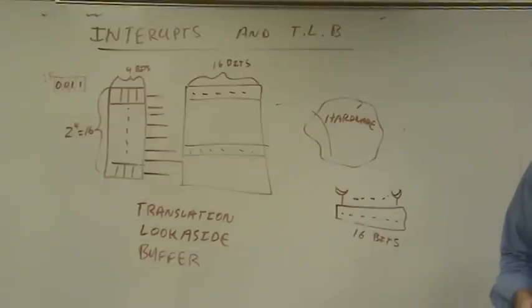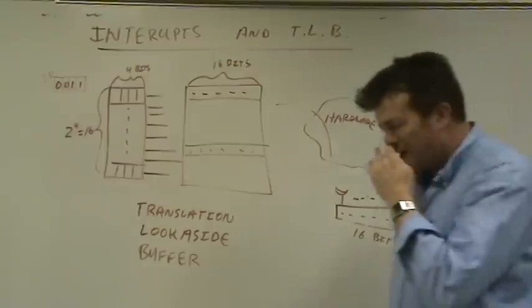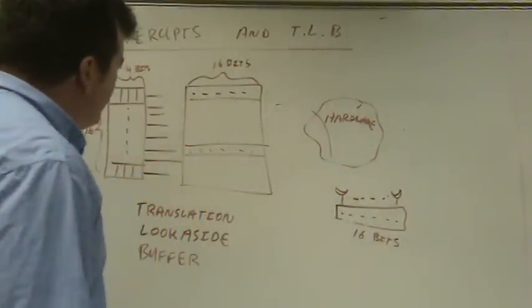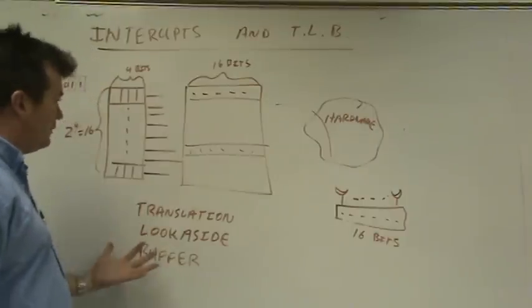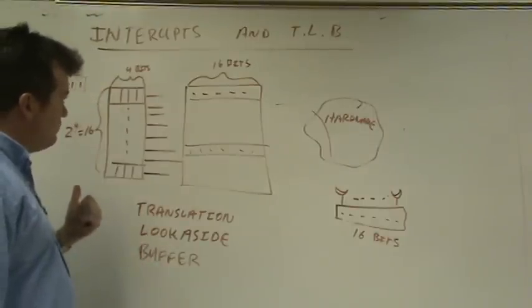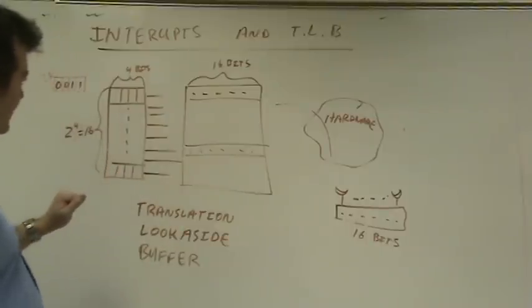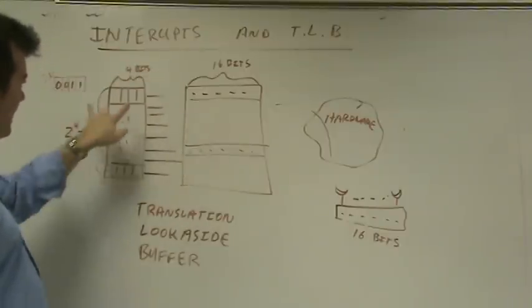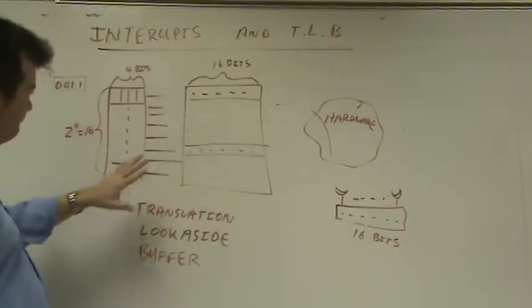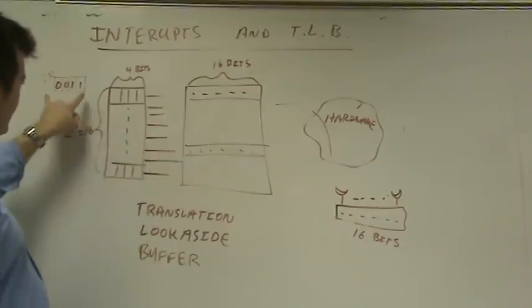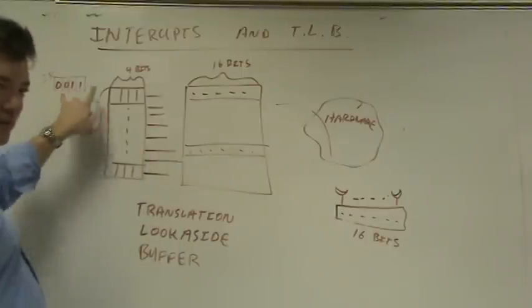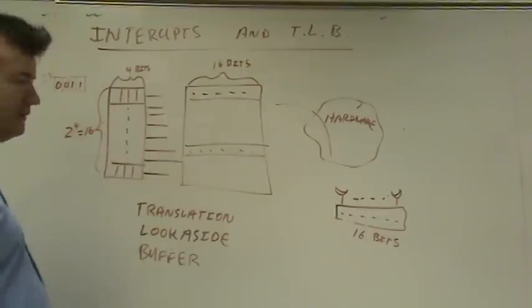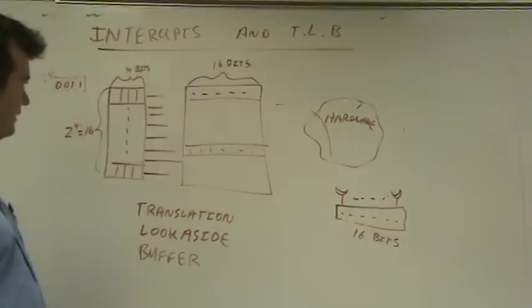Okay. So this type of hardware is not necessarily used just for operating systems. It could be used anytime we need it. But we just want to get comfortable with the idea that we can have a register, which is a collection of D flip-flops, and then have an array of registers, and we can wire them together so that we can search this set of bits looking for a match, and it'll be done instantly. Speed of electricity rather than software going through the whole array looking for a match.